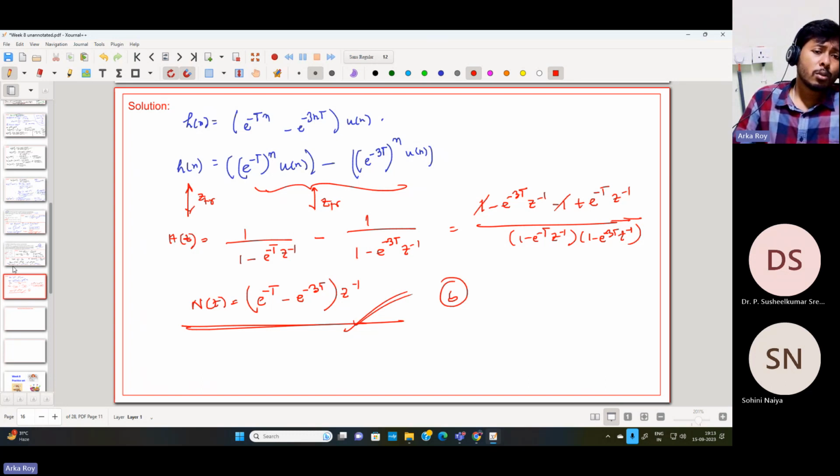bilinear transform is. A bilinear transform has this particular notion that we need to construct an f(z) where, in the analog prototype, wherever there is s, we will be replacing that s by an f(z), and f(z) indeed should be a rational function. And if f(z) is a rational function, then the corresponding digital domain transfer function will also be a rational function.